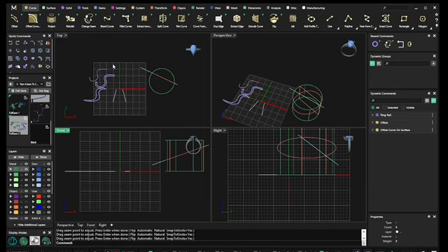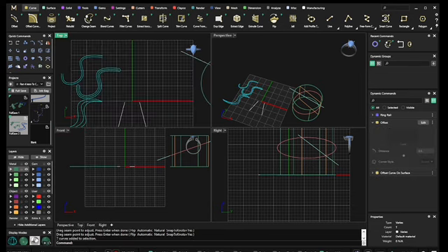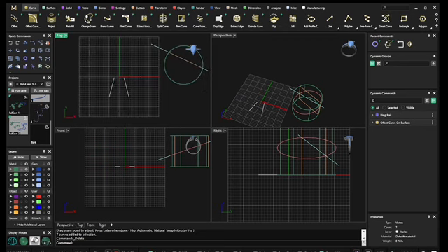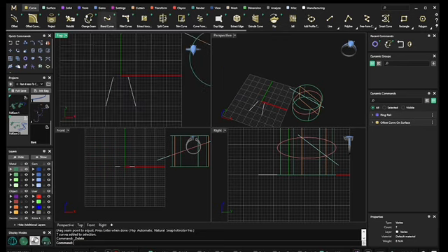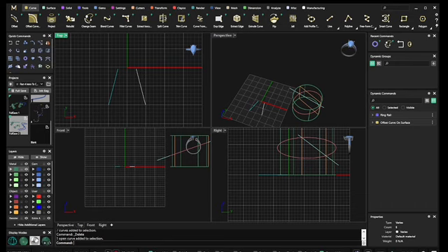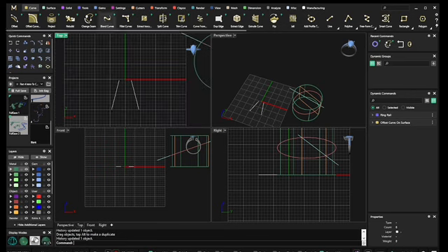I'm going to turn off the rust color in the layers so that that is not in my way, and I am going to delete these because they are in a job bag, so I have access to them. Okay, now we're at the command blend curves. All right, so these 2 curves, do you remember these? I moved them and this one was on history, so it moved as well. That's the curves. I want to blend the end of this curve and blend it together.